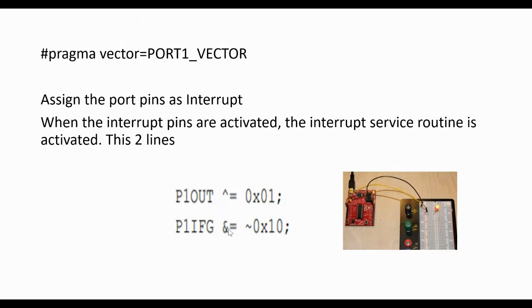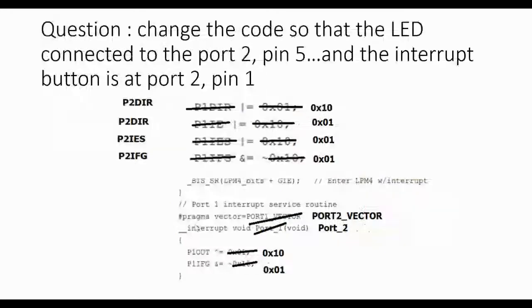This is a symbol for toggle. Now this one I already showed you guys. This one means reset, bit masking reset, which means you only want to reset the fifth pin, the flag. Again, I don't have this, but it doesn't matter, it will still work. I already told you it will still work, but the code is designed in such a way.